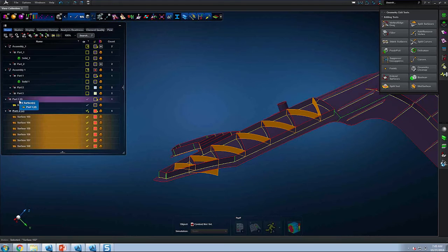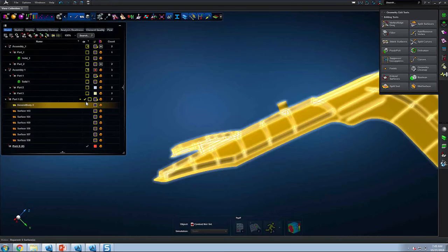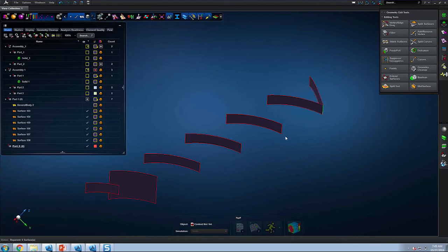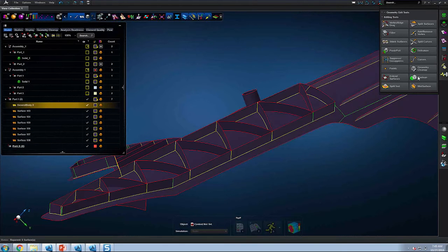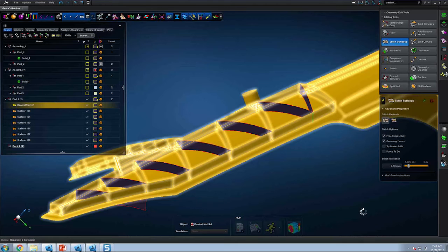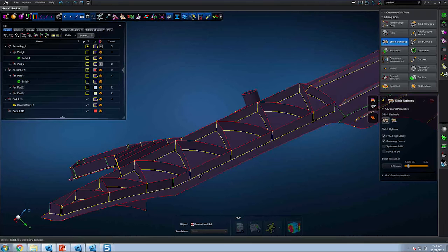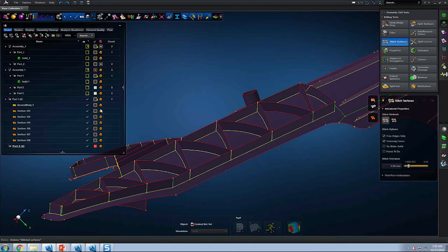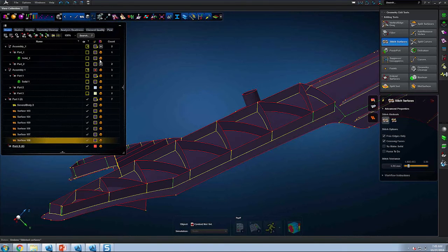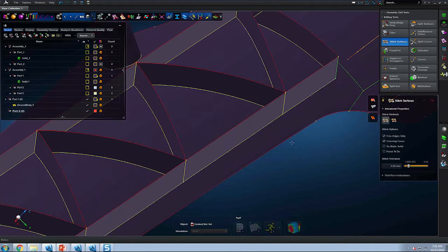And then I'll take time to go ahead and stitch all of these pieces together. Again, there are remaining free edges here at these ends, and now what I can go ahead and do is stitch all of these pieces together. So let me go ahead and drag and select all of these pieces. And now all of those individual midsurfaces that you saw a moment ago, surface 153 through 158, they were all reduced and combined to this other general body that you see on the screen. So it's now all one piece. If I inspect the model, I can see my work.